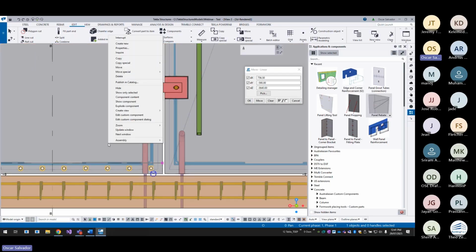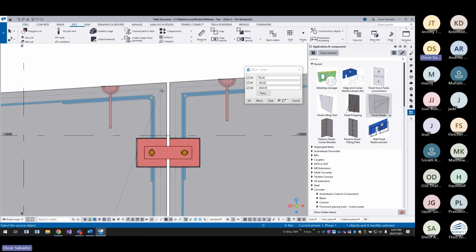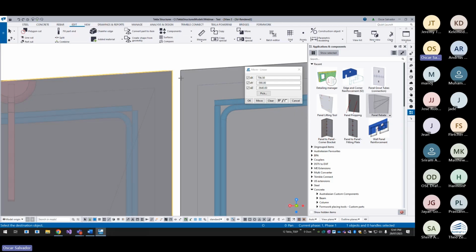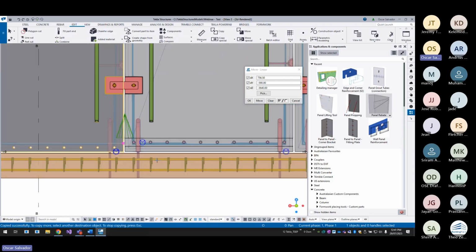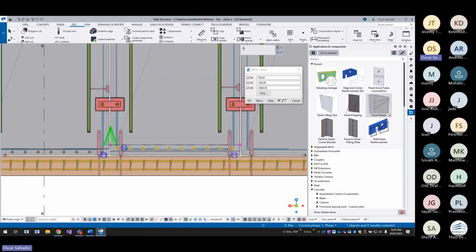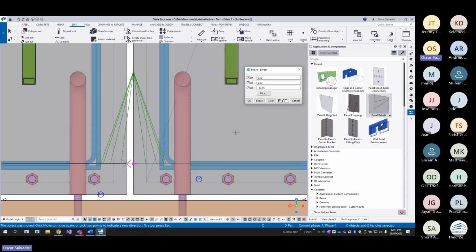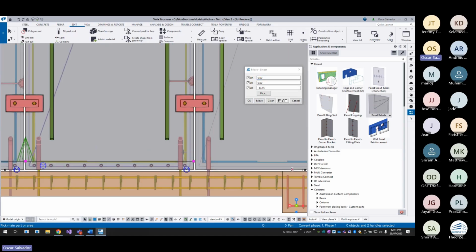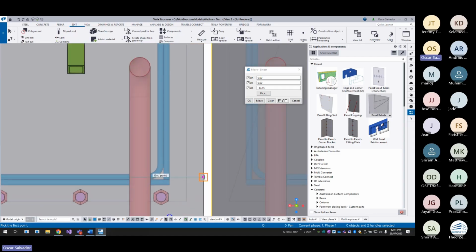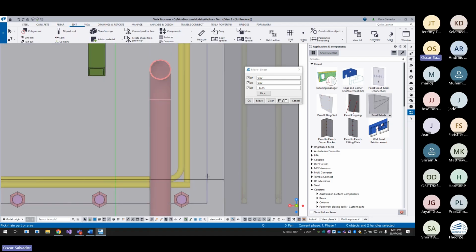And if we do copy the panel rebates, so this is my source, this is my destination, it will put the panel rebate in a different elevation, which we will end up moving the slab rebate later on. So still better to put in a slab rebate individually in this situation. So it's like a case-to-case basis.